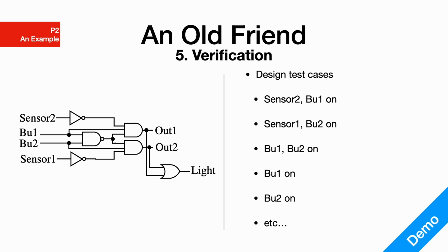So looking back, again, this is called the 5-step systematic designing procedure. We have step 1, specification, for which you have a textual description of what your system is supposed to do and a list of input and output ports. Step 2, you have formulation. Formulation deals with transforming the specification into mathematical representations, either a truth table or a set of Boolean expressions.